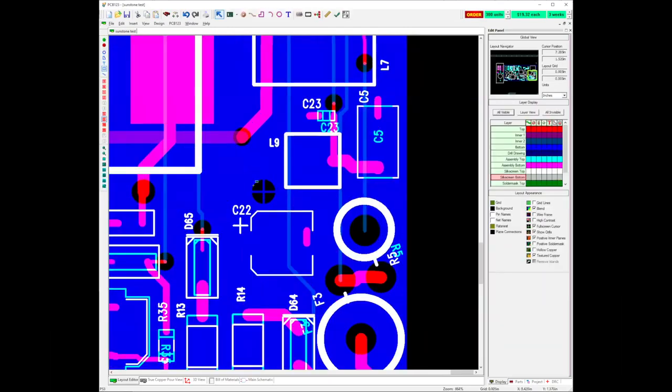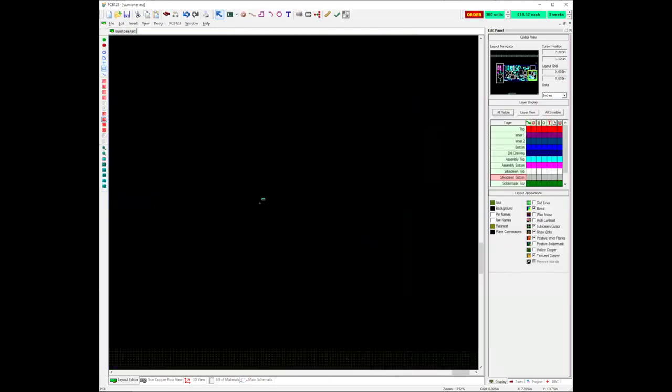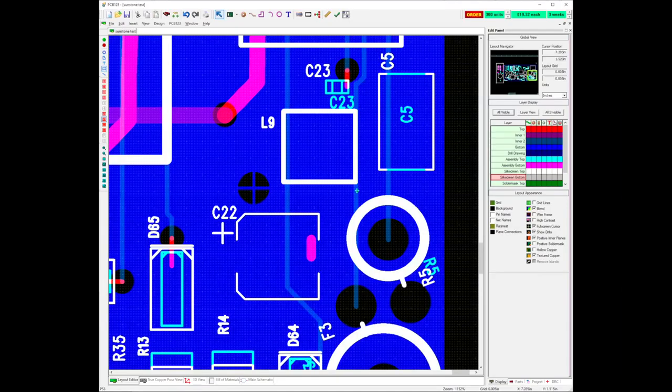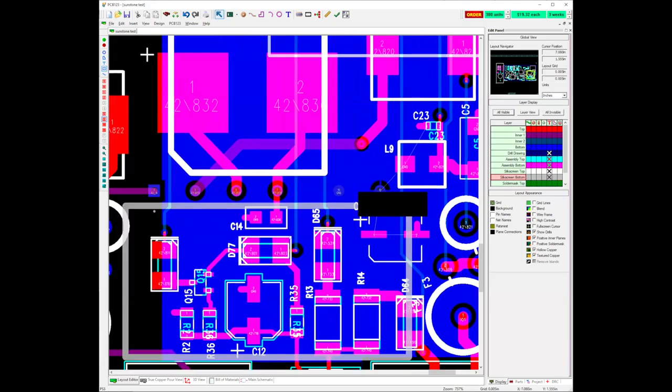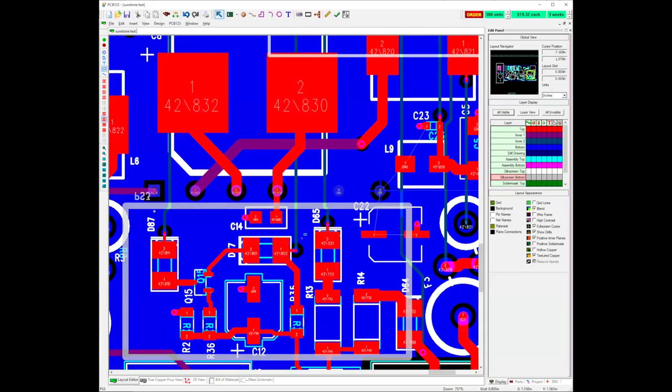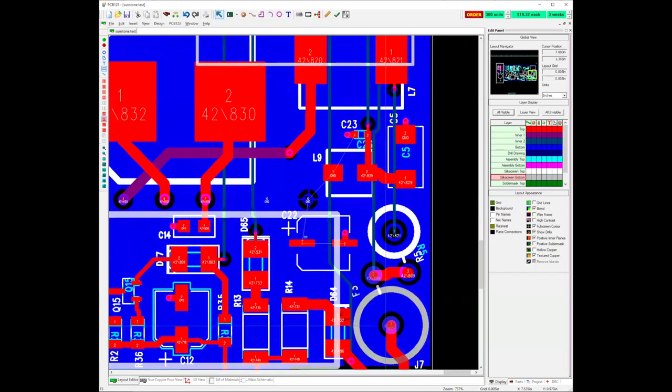You can disconnect that pin from the net if that's the pin that you want to disconnect. And if it's only one pin that has messed you up, you can disconnect that pin from the net to get rid of that incorrect connection. But on this particular one, I just made a mess of my net list. Shorted those two pins together, pin 1 and 2 of this capacitor.